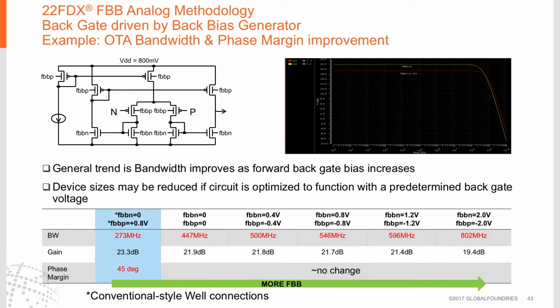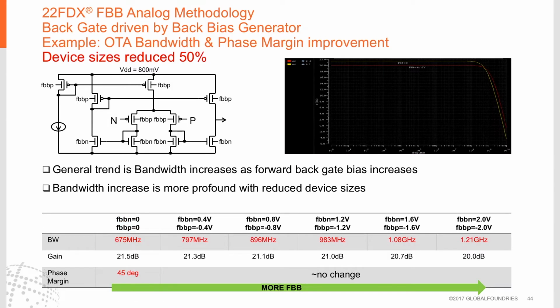With a combination of extremely short channel lengths, especially in the N-channel devices, and forward backgate bias applied, we do notice this effect. Op-amps are not normally constructed with minimum channel length devices, and if this were constructed with the more conventional channel length devices of 2 or 3 times minimum, this effect would not be seen. It's only when you get down into very small channel lengths that we observe this effect. While this may not be suitable for a signal type amplifier used in a filter, it might be very useful for amplifiers used in regulators and static situations.